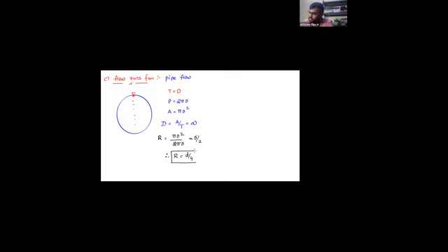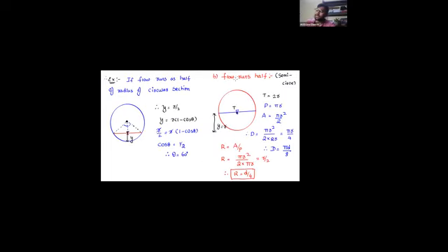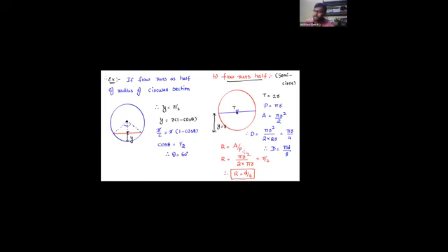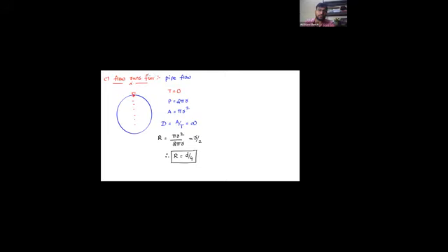So what is the common conclusion that we can get from over here? Please tell me. Whether the flow runs half or whether the flow runs full, both are going to have the same hydraulic radius. Yes or no? So when flow runs half or when flow runs full, the hydraulic radius remains the same.